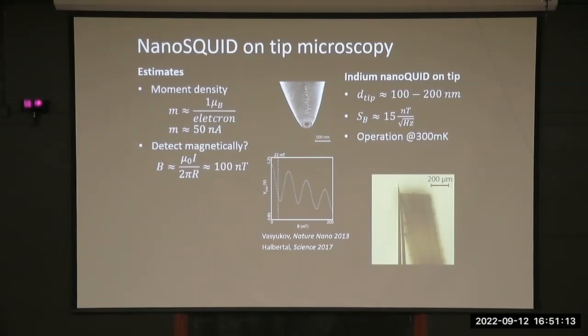Okay, and that quartz tube, that's the tip, is up there, and what's smashing into it is a quartz tuning fork from a wristwatch, like a digital wristwatch. You can actually use that to do topographic feedback, because that'll vibrate at 32 kilohertz, and then you can use that to touch the surface and figure out where you are and prevent yourself from smashing your tip.